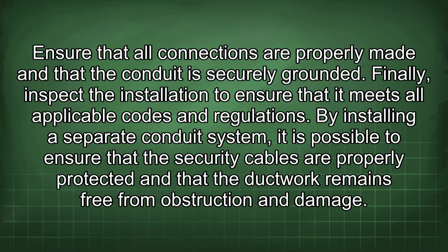Ensure that all connections are properly made and that the conduit is securely grounded. Finally, inspect the installation to ensure that it meets all applicable codes and regulations. By installing a separate conduit system, it is possible to ensure that the security cables are properly protected and that the ductwork remains free from obstruction and damage.